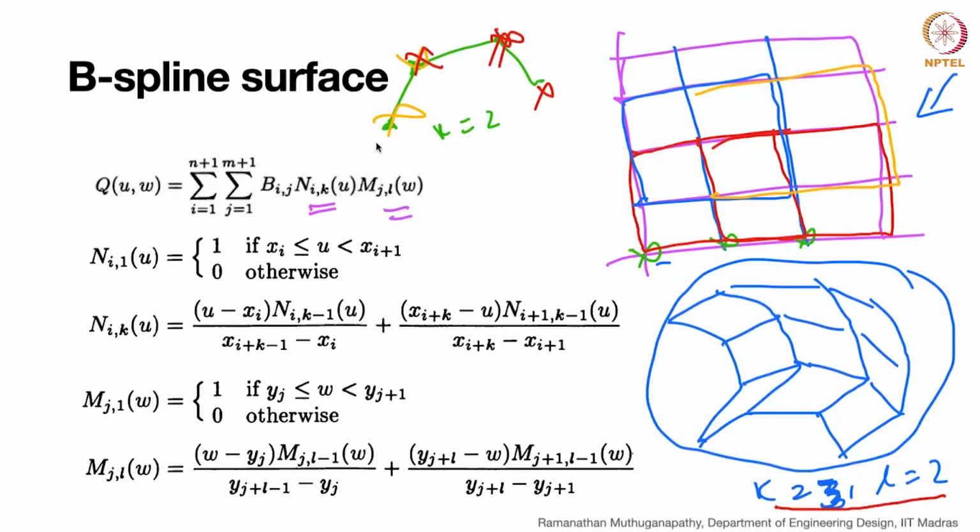Remember that? Did you guys remember that we saw some of the convex hulls overlap, but the curve will not overlap? Isn't it? Yes, sir. Similarly here, the convex hulls of these individual control nets may overlap, but the surface will not overlap. They will have a clear-cut distinction in the parameterization. That is the idea. Okay, I think more than that may be a little too much.